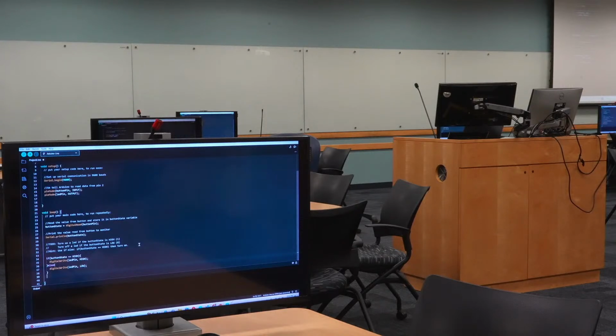Okay, that's interesting. Is it working? I'm checking if I did something wrong. Did you upload the code to the Arduino, like clicking the arrow button? It's giving me a compilation error. What does it say? Expected initializer before end.